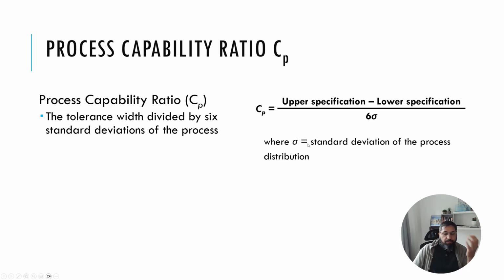So how do we get sigma? We set up the process in its ideal state. So we have fresh machines, lubricated, with maintenance taken care of. We check every single part. Everything is fine. Nothing is worn out. They're operating as suggested by the manufacturer of the machines. We have fully trained, experienced workers. We have tested all the raw materials. They're all fine. Temperature, everything is perfect. It's like a laboratory control type of setting.